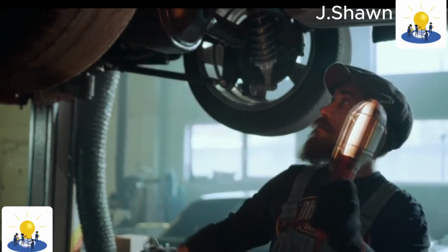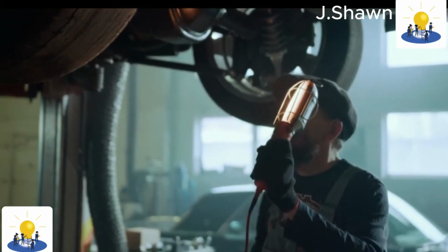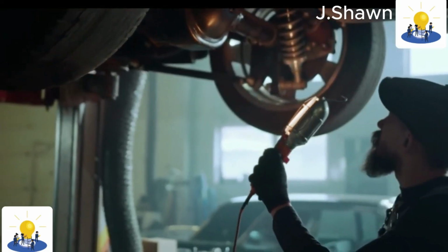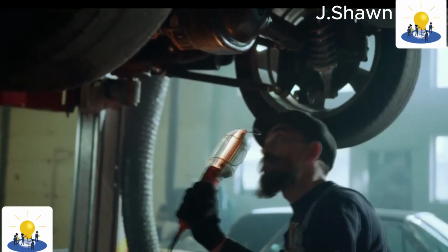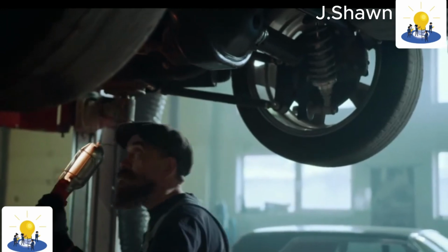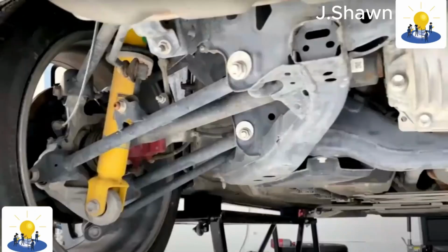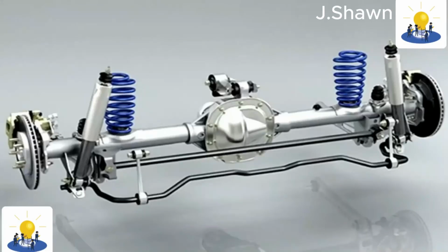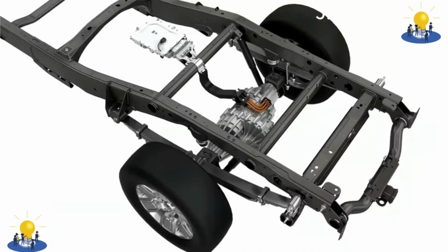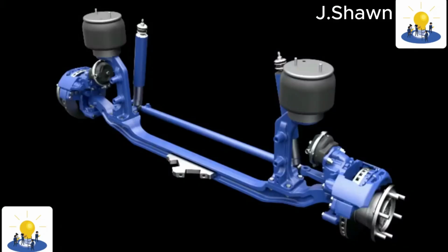The bulky differential housing of a Hotchkiss live axle reduces ground clearance, hindering the vehicle's ability to ford deep mud, clear obstacles, and negotiate deeply rutted roads. The differential housing can only be raised by using larger wheels and tires, typically with a penalty in unsprung weight, braking effectiveness, and acquisition costs. Furthermore, vehicle modifications may be necessary for adequate fender or frame clearance.